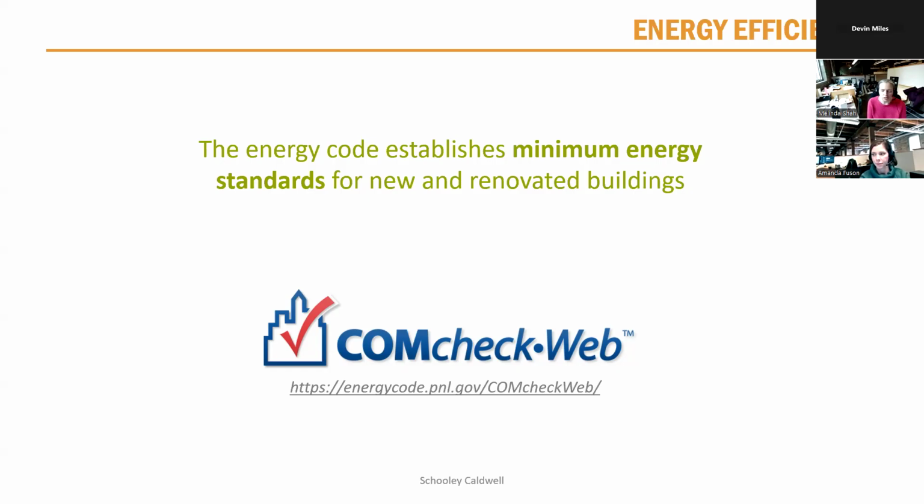Eventually, in most jurisdictions around Ohio, to show that you are compliant with the energy code when you go to pull your building permit, you can either do energy modeling, which requires complex software, or there's also something called ComCheck Web, which allows you to put in the size of your building, what the walls are made out of, and it will start doing a lot of those calculations for you. It's pretty useful, especially in smaller buildings.